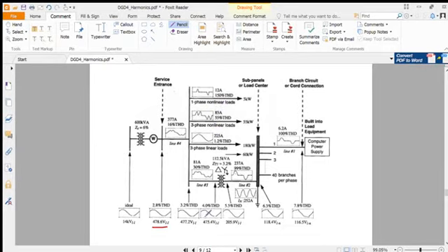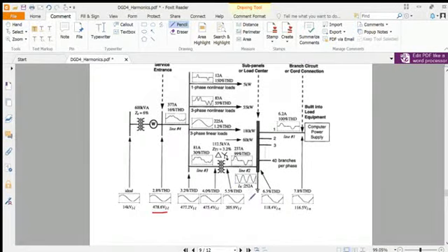Here the total harmonic distortion, THD, is increasing, and the shape of the signal as well as the voltage is getting reduced. Eventually at the receiving end we are using our laptop. Here the shape is a complex periodic wave, a harmonically distorted waveform. The harmonic percentage is increased, so the shape as well as the voltage amplitude is reduced. This is the typical scenario in our house.